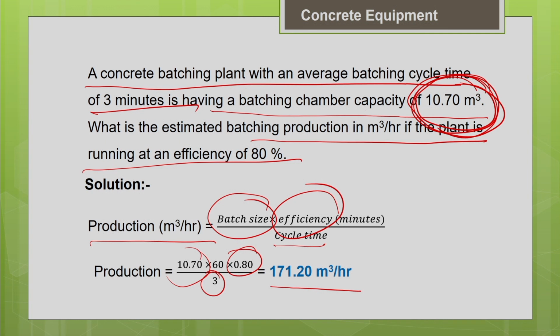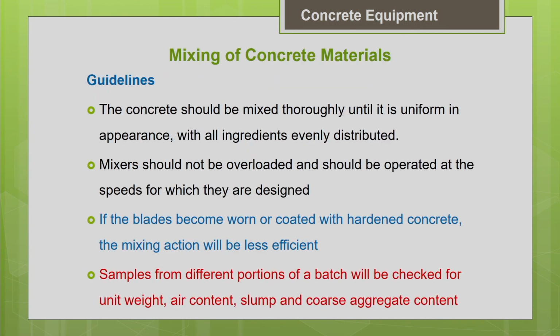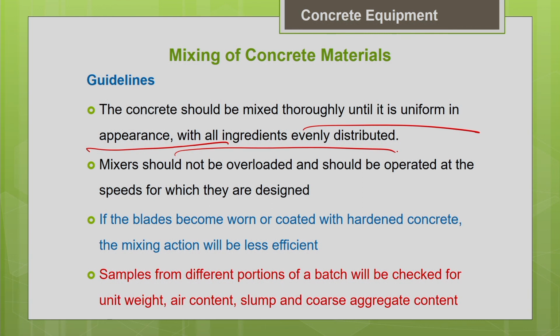So, now let us look into some general guidelines with respect to mixing of concrete. So, you should mix the concrete thoroughly, as I told you, until it is uniform in appearance. So, based on experience, by looking at the color itself you can make a judgment whether the concrete quality is good or not, with all the ingredients evenly distributed. That homogeneous mix is very important. That is why I told you we should go for at least the minimum duration as prescribed by the manufacturer. You should never go below the minimum duration.